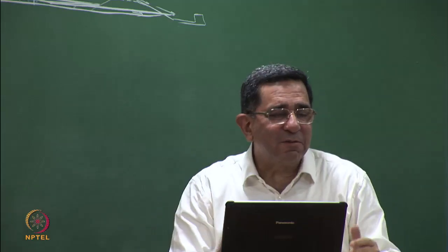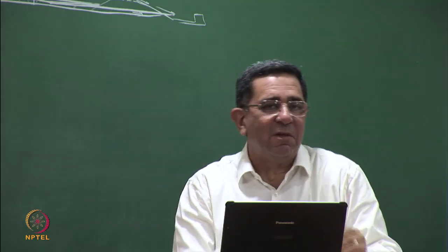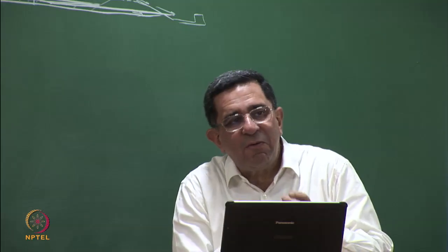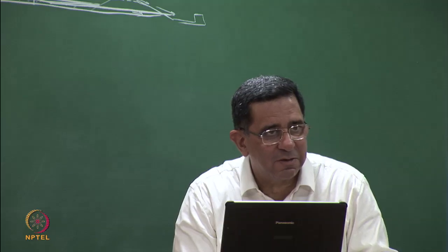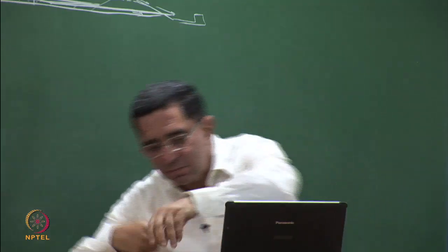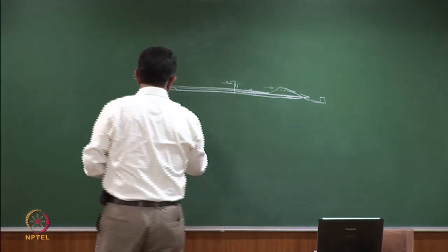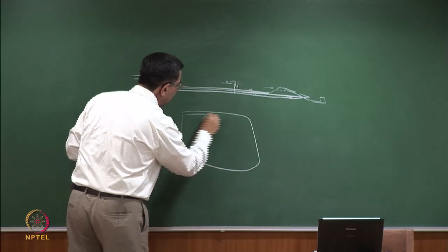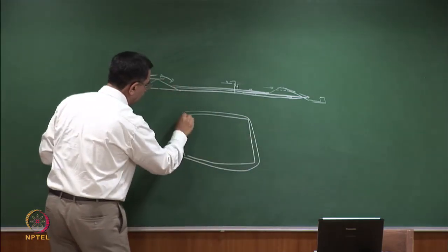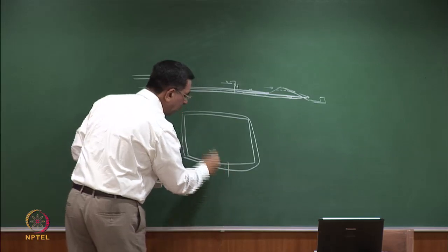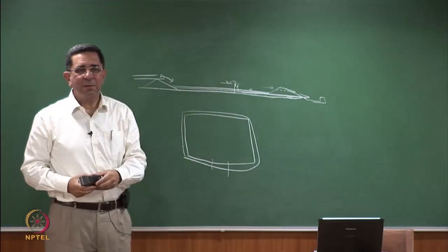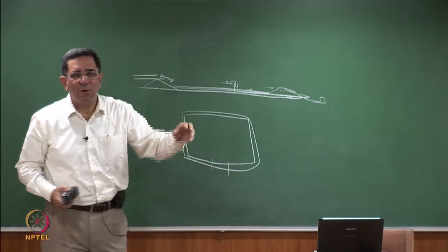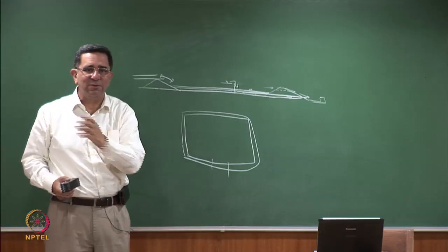And many a times this problem has been referred to IITs, and we have been asked, can we put a filter embankment? That means let us have a flexible system. What's a flexible system? I have a ring impoundment, and this is my embankment. Let's make this portion a porous embankment. Porous embankment means one which allows drainage. Water flows through it, but it does not allow the ash or the tailings to come out.